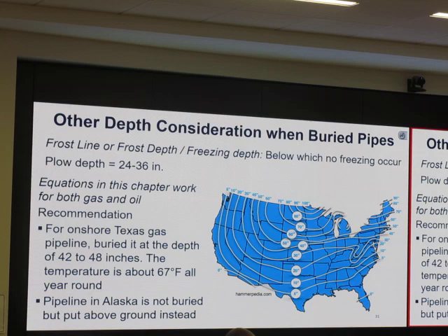The guideline is, okay, let's say we are over here. We buried 5 inches. Is that good? It's good for the case of not getting freeze. Okay, but it's not good for the farmer. When they grow cotton, they will break the pipe. You have to bury it deeper than that to prevent them breaking the pipe. Okay, 3 feet. I think 42 inches is good enough. Okay, so in Texas, the worry is not about it getting frozen. The worry may be about the cotton field damaging it.